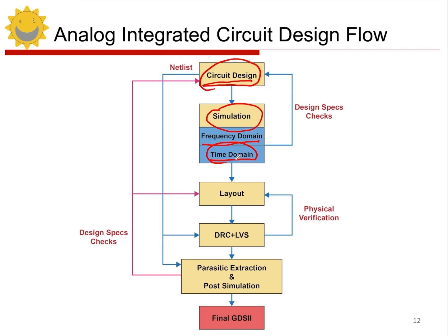This is the analog circuit design process. So, we need to perform a time domain simulation to see actual signal waveforms. Here, we check if the simulation results align with your design specifications, i.e., design constraints and parameters. If they don't match, you must modify your design. If they do match, proceed to layout.